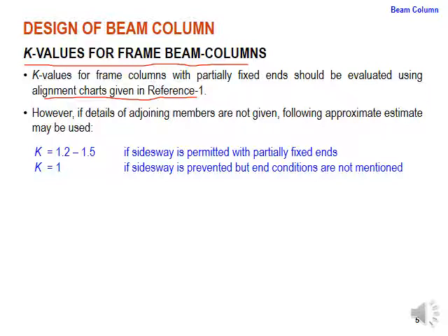Once the top end and the bottom end G values will be with you, we are going to calculate the G or psi values, and we align the left and right parts between top and bottom conditions. Finally the in-between chart, you get this kind of chart in the LRFD manual. So here you have the K value for your column.